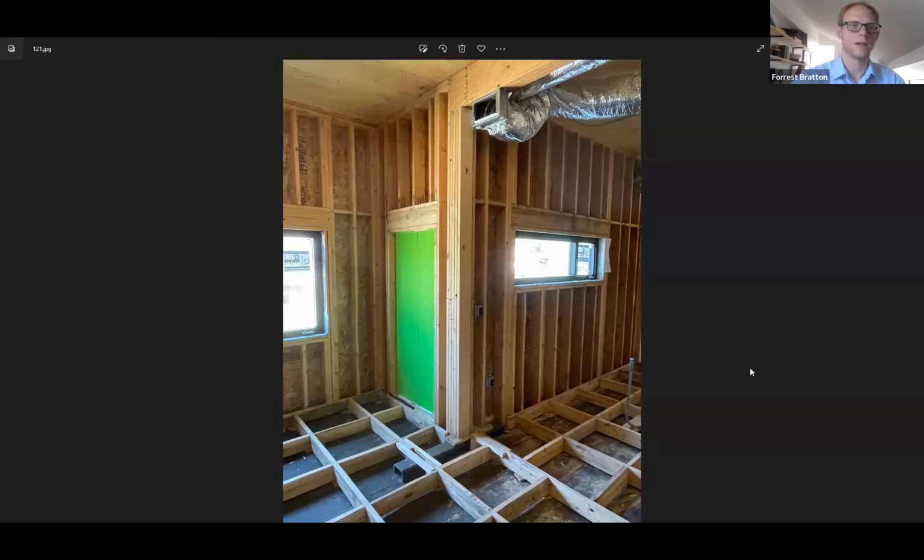We would have been in a situation where you're adding intermediate beams as another layer within the structure at the podium. So you're increasing the structure depth probably significantly, a foot or more.